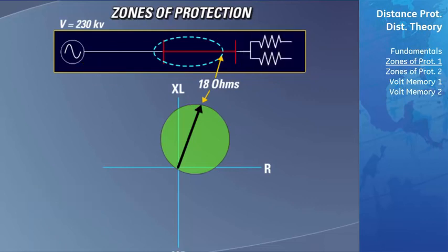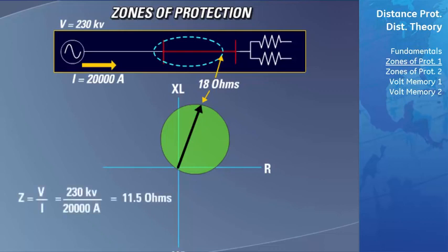If a substantial amount of load is added to the power system, the current needed to feed the load increases substantially. Even though there is no fault on the transmission line, the newly calculated impedance of the line would be less than the reach of the mho circle zone. However, since the load that was added is mostly resistive, the plotted impedance point would be much closer to the origin of the graph, but still very close to the x-axis, as seen here.